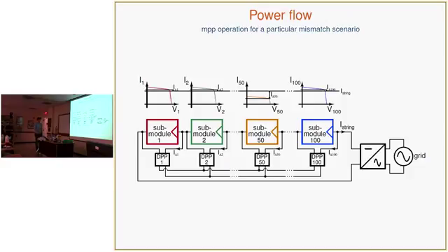So say, for a 100 submodule connection, submodule 50 is mismatched. All of the strongly performing submodules that have the same illumination and generate the same power would need to inject power through the bus, and then DPP50 would need to absorb that power to operate at its maximum power point. And you would need to bring down I string a little bit. So if I string were equal to the maximum power point current of all the submodules except for submodule 50, then